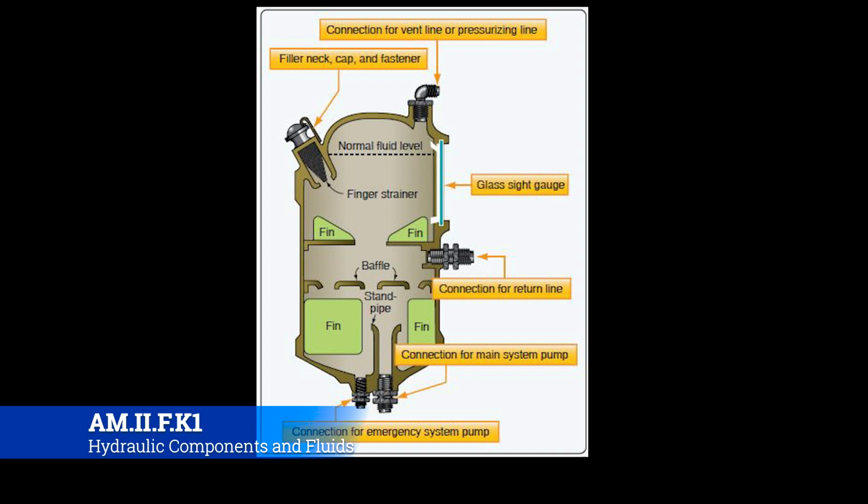Now, most of the time your hydraulic fluid is by nature not going to expand or contract that much, but you never know what you're going to end up working on and what the properties of that particular fluid are. 5606, Skydrol, that kind of thing, they're not going to expand or contract that much, so you don't have those concerns. But like I said, you never know where you're going to go. So that's a good rule of thumb. Any type of servicing, you always want to make sure that the conditions are correct for the servicing to happen, so that way you don't make any kind of mistakes. But yeah, that is what a sight glass is.